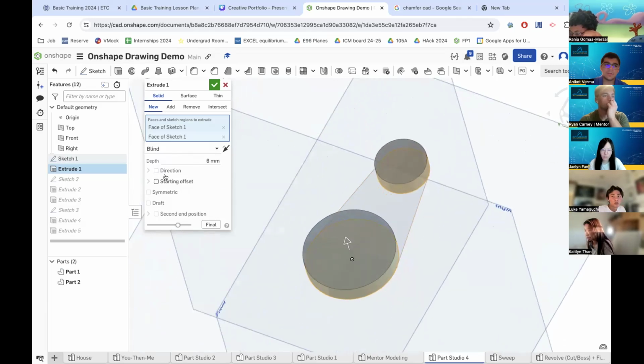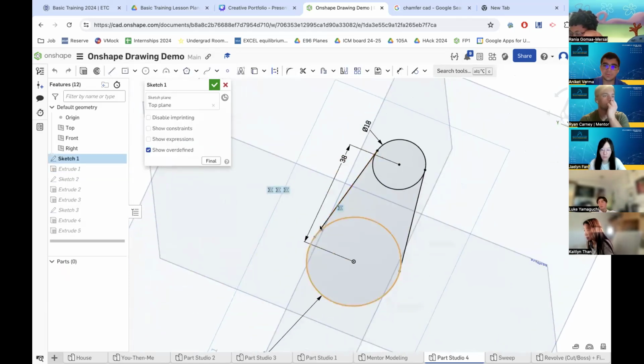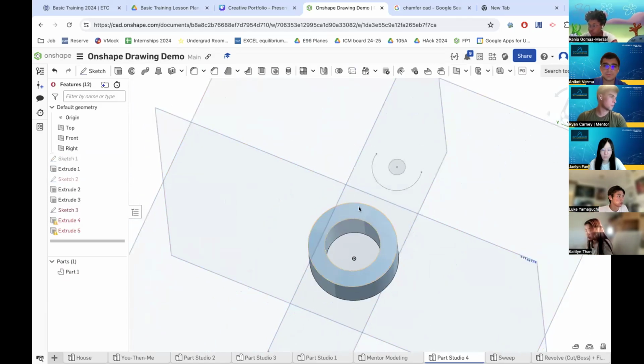Okay, so that probably means that in the first sketch you drew, there's something which is not part of the line, which is not actually connected to your circles. So I'd go back to the first sketch and look if there are any issues related to that. Once the sketch is complete, the middle area should become grayed out and you should be able to select it. I see, I see. Thank you. Yeah, of course. Oh, I broke mine.